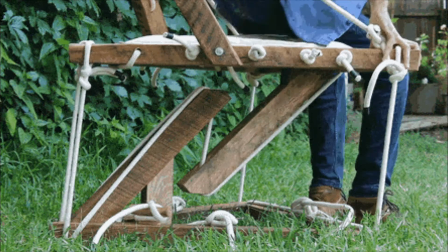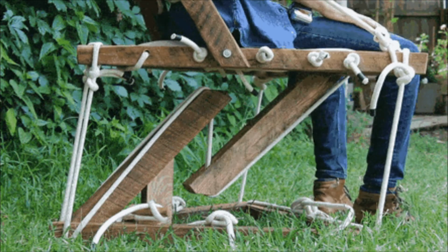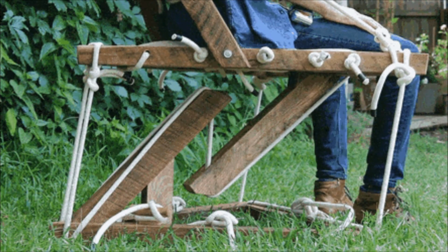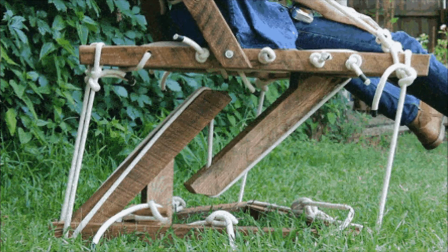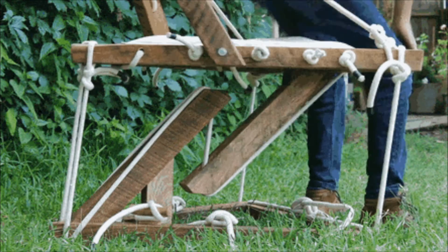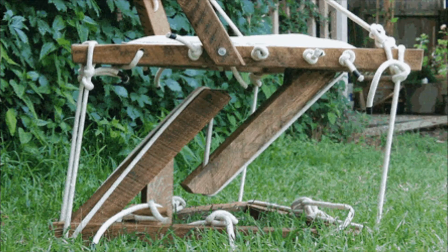The difficulty in creating a tensegrity structure for this purpose, however, lies in the stability and strength of the members in tension. The more weight you place on the top surface, the more unstable the balance becomes, and at a critical point, the entire structure can twist and collapse under the weight.